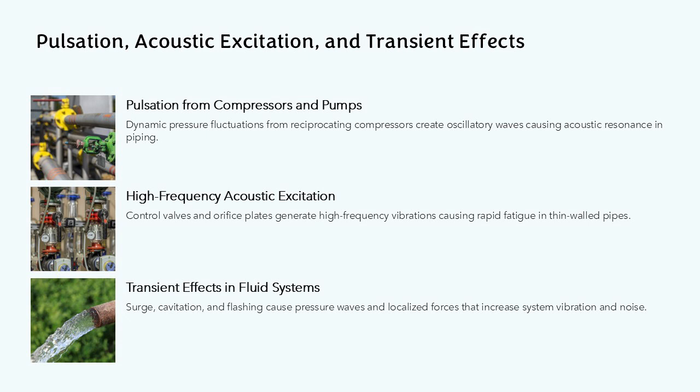High-frequency acoustic excitation, often associated with control valves, relief valves, and orifice plates, poses a unique challenge due to its ability to induce rapid fatigue failures in thin-walled pipes and small-bore connections. These failures can occur within hours of exposure to high-frequency vibration.